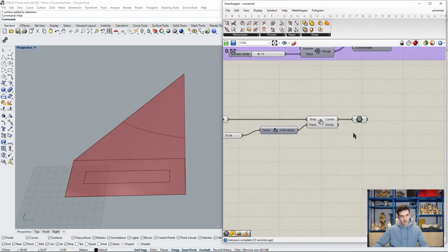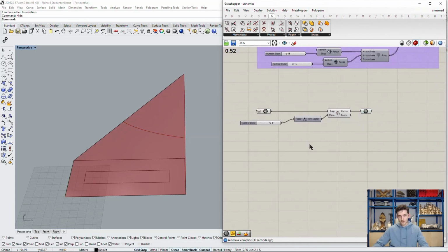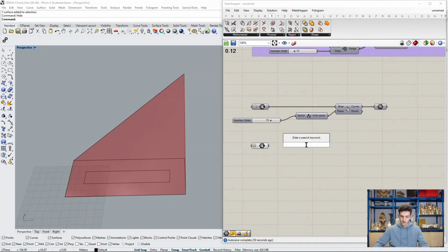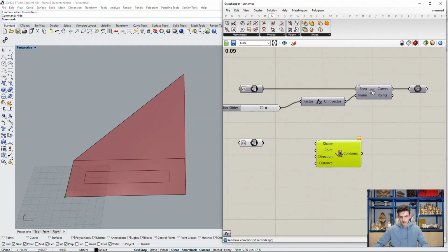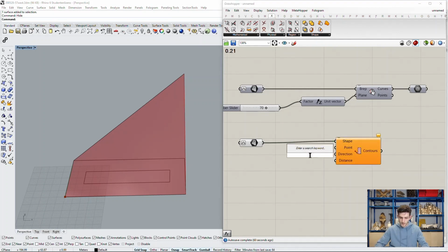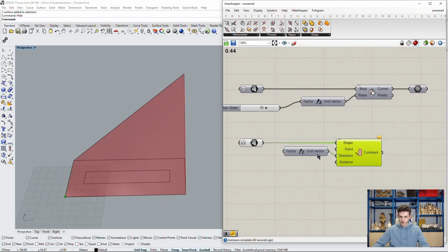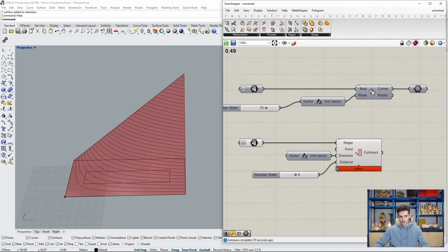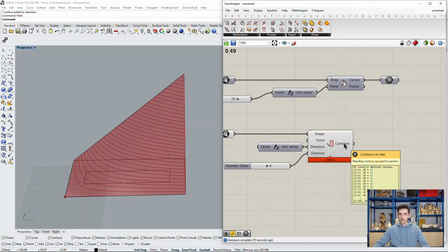You may recognize this technique, and you're absolutely right, if we use the command contour, it will do this exact same thing with a predefined distance between these planes. Just like this. So we would have the lines we need to define the floors of our building.